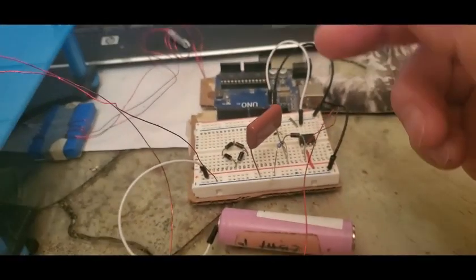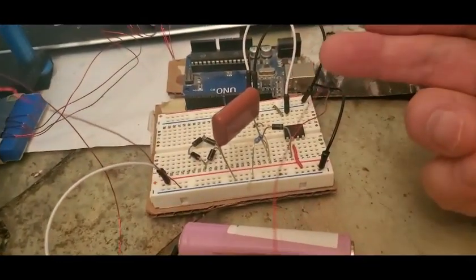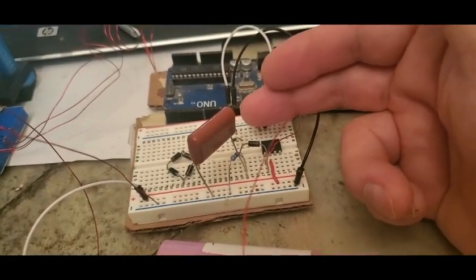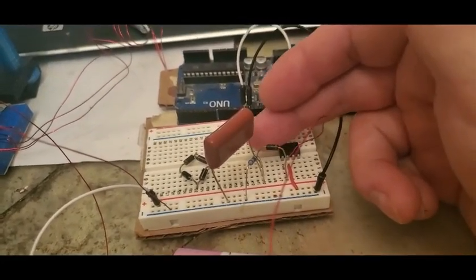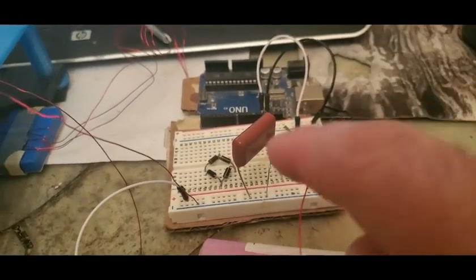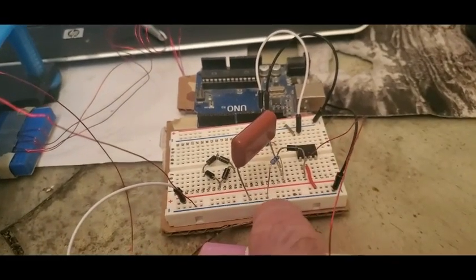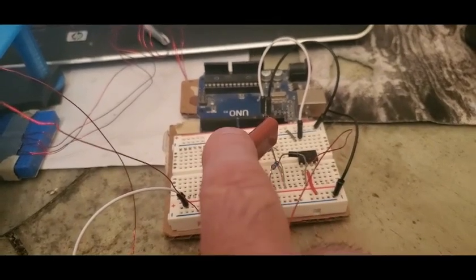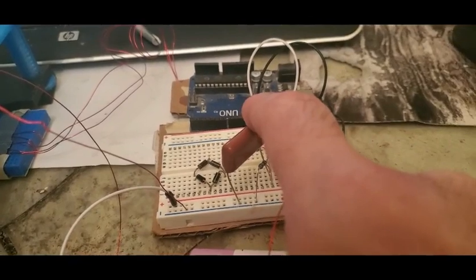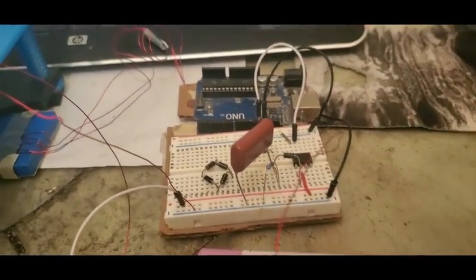So again, when the coil collapses now, reverse energy, opposite polarity electricity, can now flow through here and end up in the cap. And one funny thing is this is the negative bus line, but this becomes the positive of the cap, and the negative of the cap's over there. And so that's how you capture it.